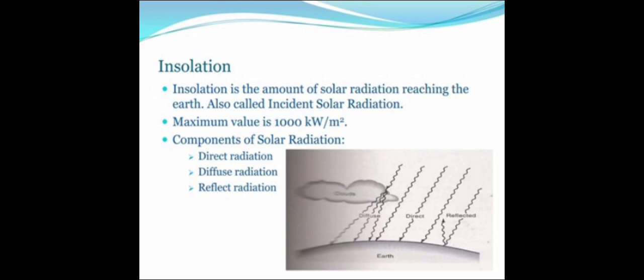This value is averaged to account for differences in the day's length. It depends upon the below listed parameters: atmospheric clarity, hour angle, seasonal variations and geographic location of the particular surface, degree of latitude of the location, area of exposed surface, angle of tilt of the solar panel, shadow of trees, tall structures,